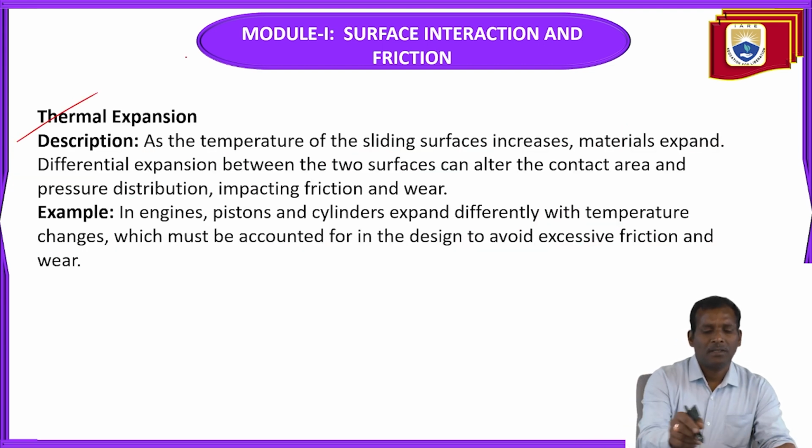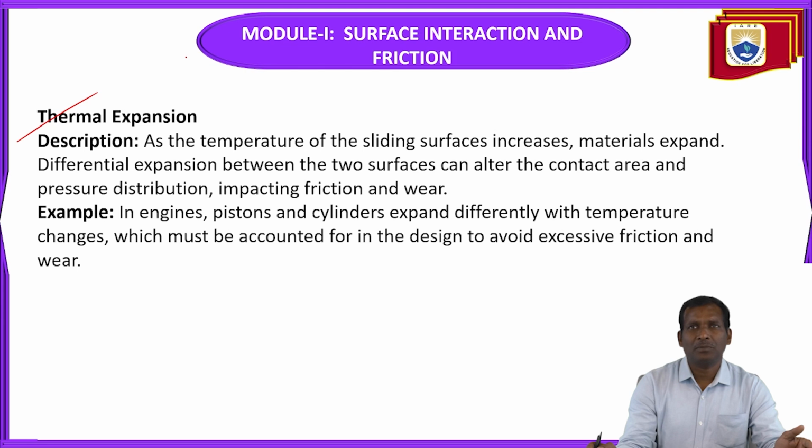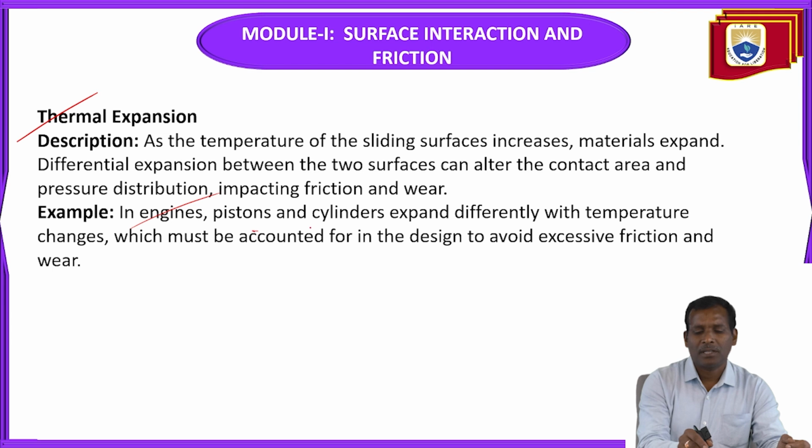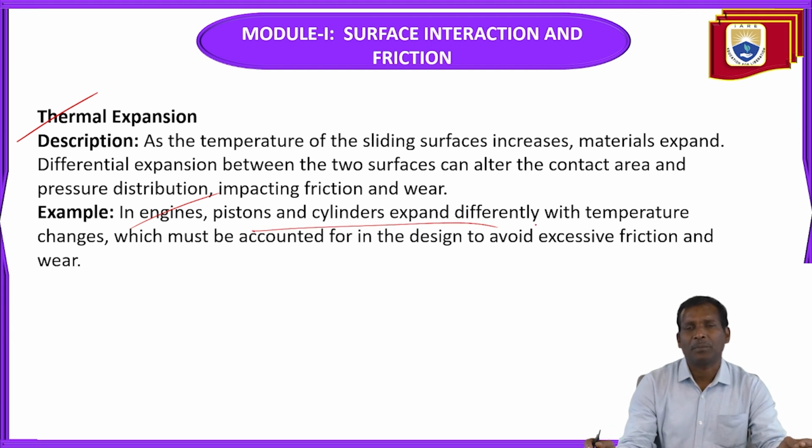Thermal expansion. As the temperature of the sliding surfaces increases, materials expand. Differential expansion between the two surfaces can alter the contact area and pressure distribution, impacting friction and wear. An example shown here is in engines, where pistons and cylinders expand differently with temperature changes.